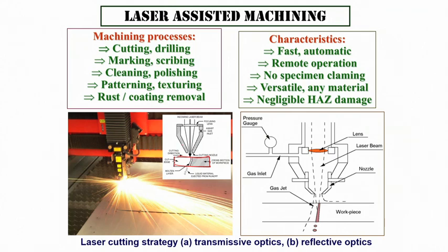And when the beam interacts with the solid, it can create immediate vaporization, and depending on the interaction time, the depth of cut will be determined, and there has to be a relative motion. Either the solid moves or the laser beam itself with the nozzle moves.